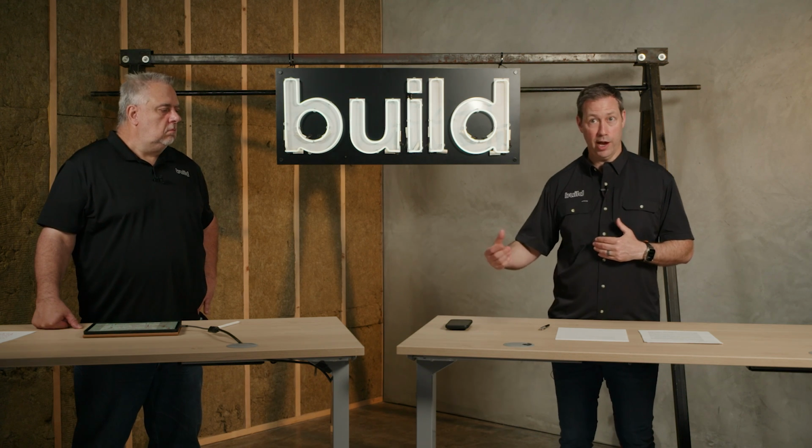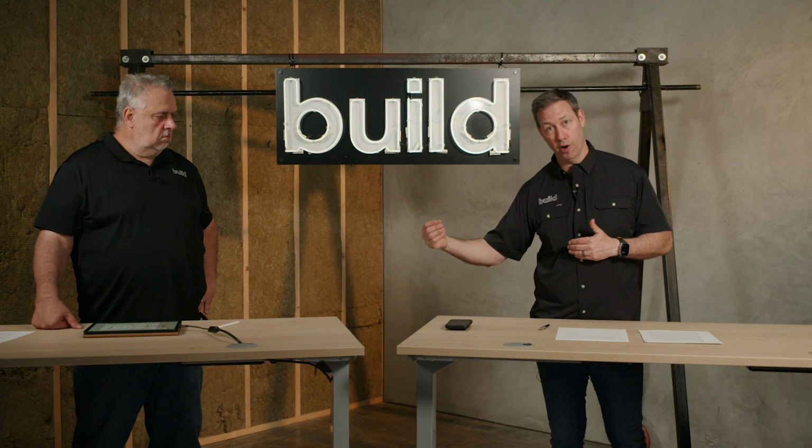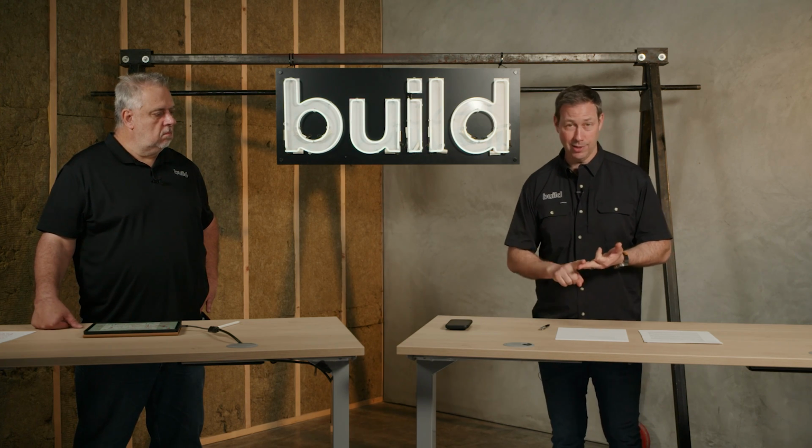So we need to think about those components that go into our system and the level of exposure. A one-story house built in the plains, standard house wrap, standard off-the-shelf materials, probably going to work fine as long as that house has overhangs. Two-story house, no overhangs, modern architecture, we've got to spend a lot more money on the WRB system, the drainage plane system. We also have to spend more money on the window and door package, and we've got to make sure that all those flashings, all those details were done with the best and most knowledgeable labor to understand how to install those correctly, because the smallest amount of error in those buildings will cause a problem.